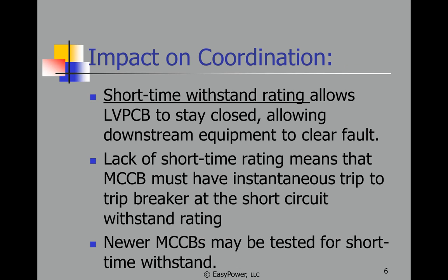All right, let's get back to coordination since that's what we were supposed to be talking about. We talked earlier about the short time withstand rating that the low voltage power circuit breaker has, and that allows it to stay closed and allows equipment downstream of that to clear the fault before that breaker trips, which is what you want. That's coordination or selectivity. For the molded case circuit breakers, I don't have that short time rating necessarily, so it has to have an instantaneous trip. And that's going to limit our ability to coordinate between molded case circuit breakers in series, upstream and downstream. And we mentioned that the newer molded case breakers may be tested for the short time withstand, but it's not a part of the standard at this point.